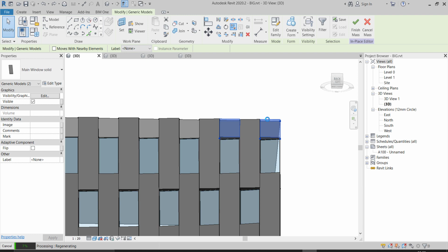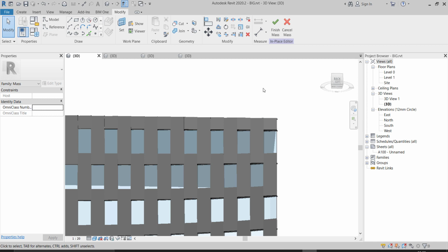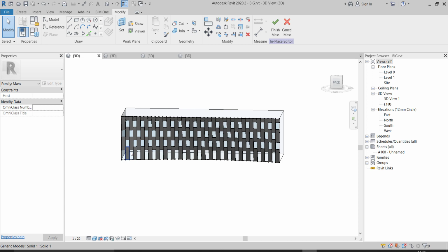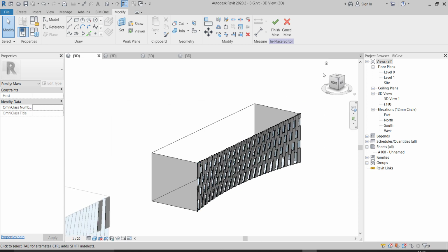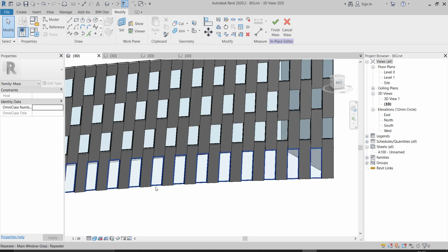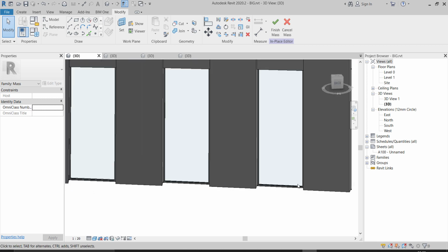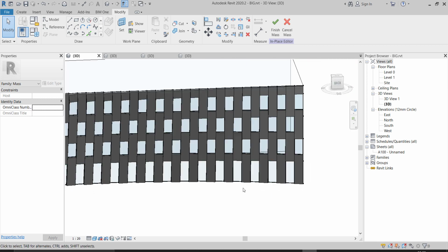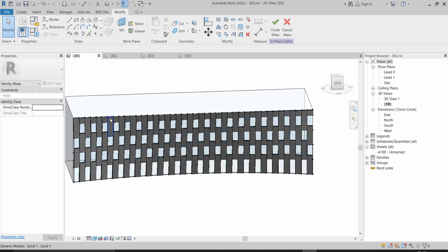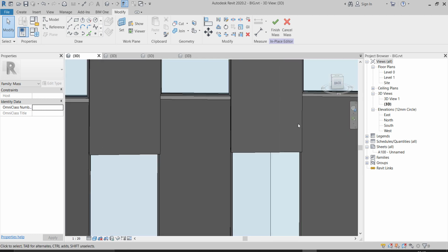and create the repeater. The repeaters are really funny in Revit because sometimes they are really unpredictable. And that's how you make the facade here. And I want to show you why it is important to have that made as an arc. It is the distribution, the division of equal segments here and here that makes the geometry aligned nicely.